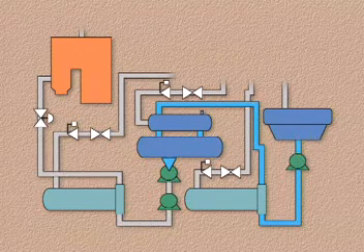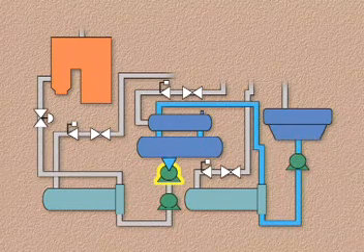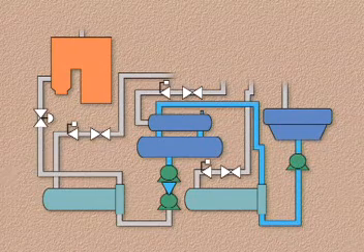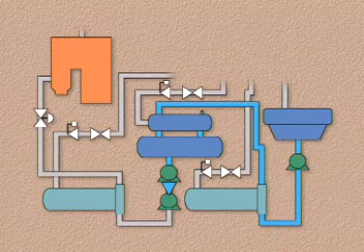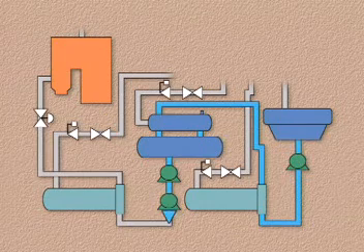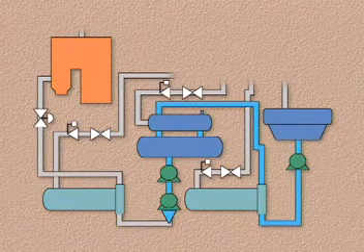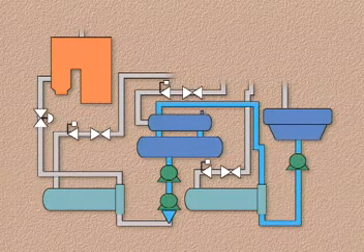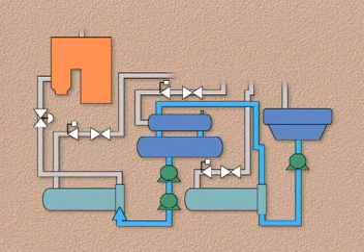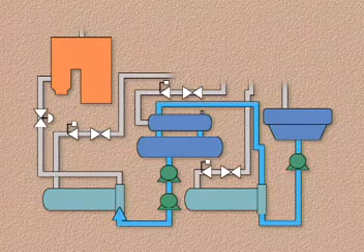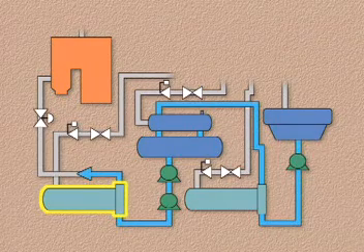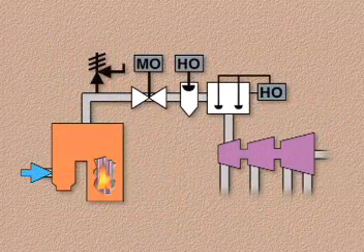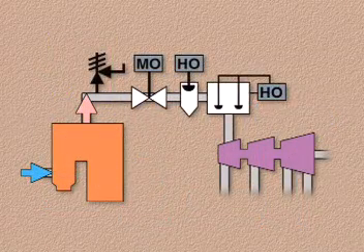From the storage tank in our system, the water flows to a condensate booster pump. This pump increases the pressure of the feedwater and moves it through piping to the boiler feed pump. The boiler feed pump, sometimes called a feedwater pump, also increases the pressure of the feedwater. The additional increase in pressure moves the feedwater through components such as feedwater heaters, piping, and valves to the boiler. Finally, in the boiler, the steam-water cycle begins again.